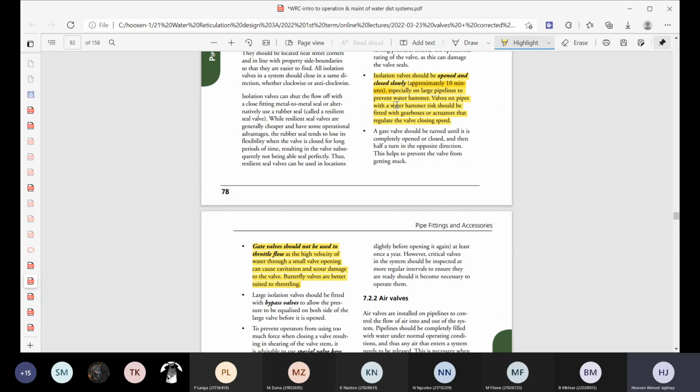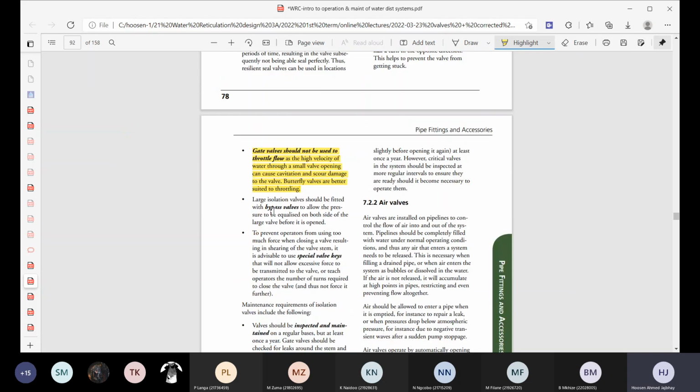Right? And that's the water hammer. That's what's happening. You get that surge. If you ask somebody to do it and you stand outside on the pipe, you will feel that pipe move. You'll actually feel the vibration, the knock on the pipe. Right, so that's just from a practical point of view. Please don't do this more than once or twice, or you might end up with a leak at your house.